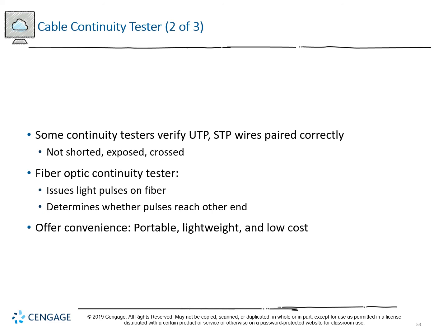Now, if they do not, if it seems to be kind of flickery, or if it seems really weak, then there may be a problem where maybe you have a break or a bounce back point due to the bend radius.